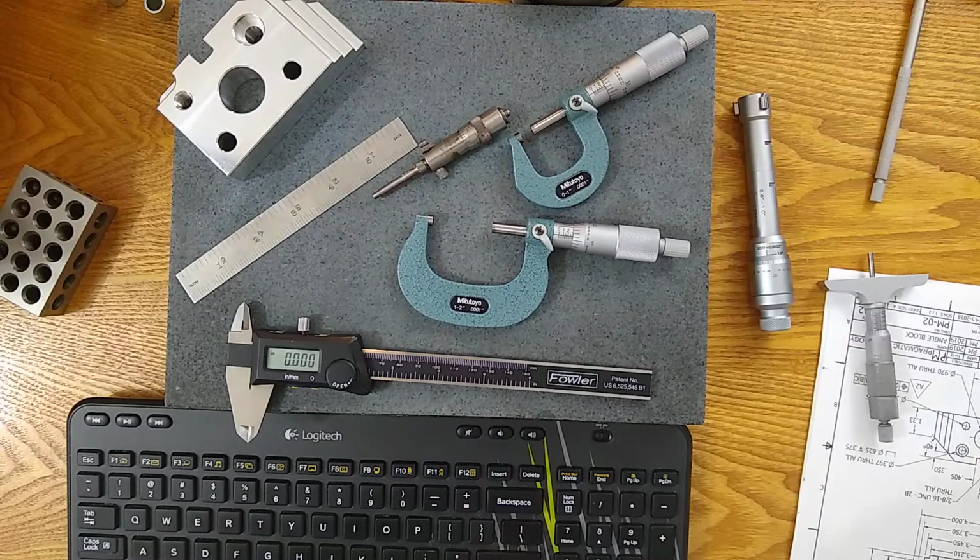Resolution feeds directly into the total uncertainty ratio on the right column there. So this resolution is directly proportional to the uncertainty ratio. So 3-to-1, 4-to-1, or 10-to-1. You essentially multiply 3 times the resolution, or 4 times resolution, or 10 times resolution. So I'm giving you a few of these. And this is going to be your minimum size tolerance zone.